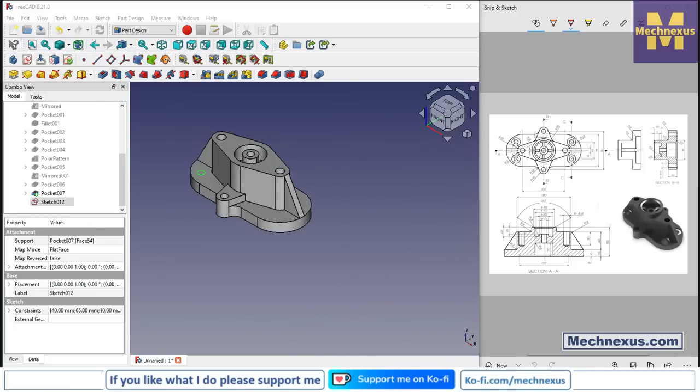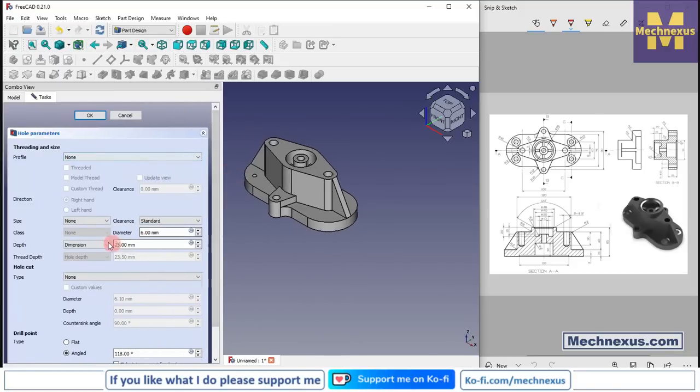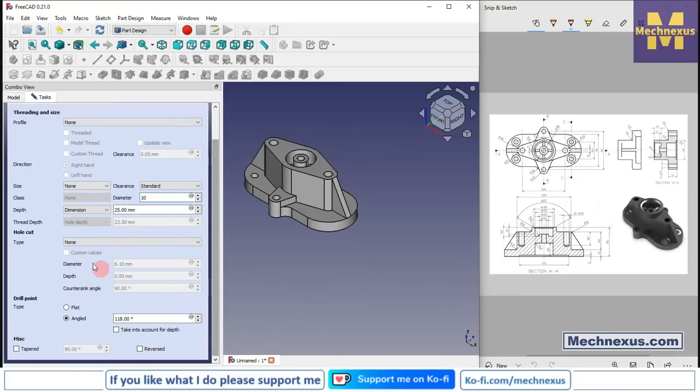we will provide the counter bore holes. So select the sketch and click on the hole wizard, and here select none, and here is of diameter 10, and from here we will select a counter bore, give here value 20 with a 2 mm depth.